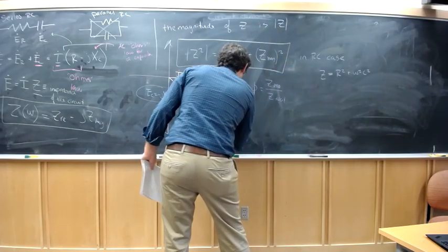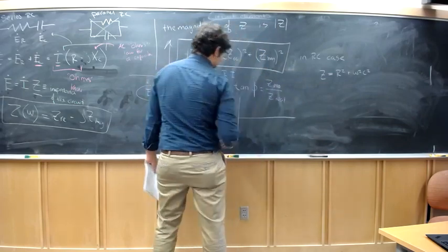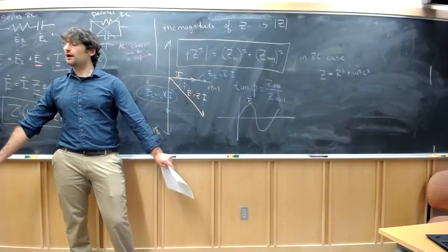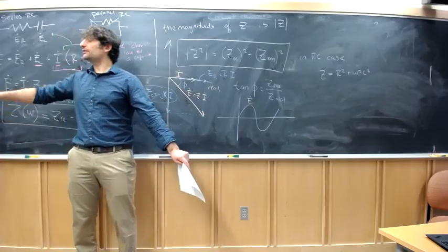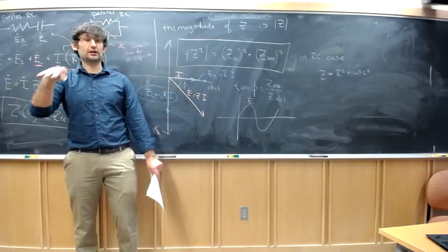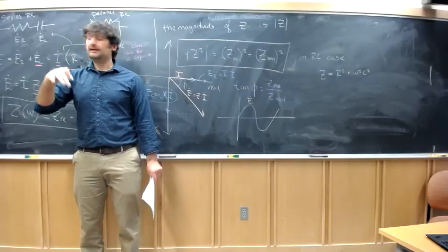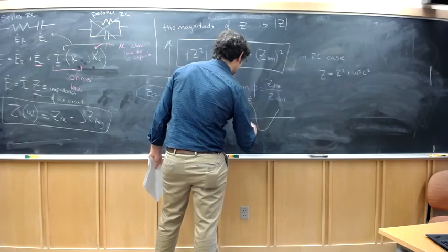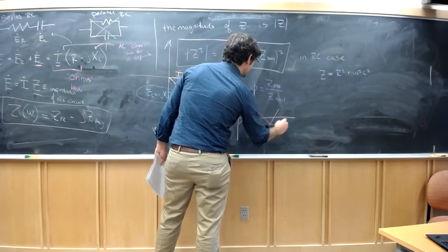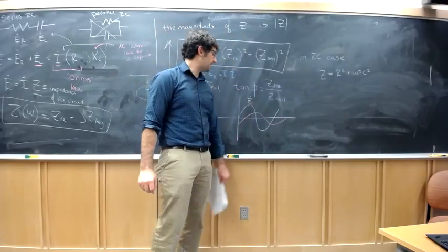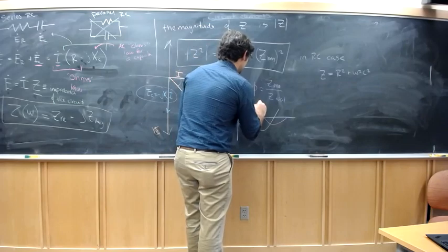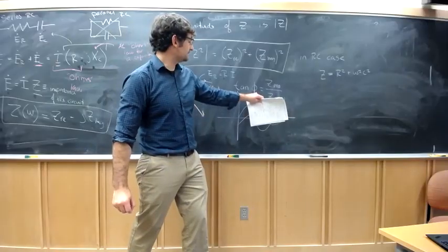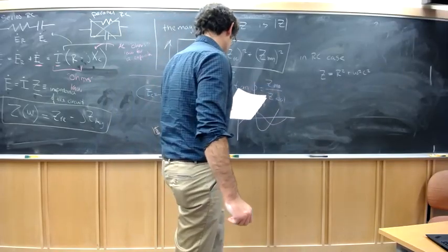So let's think about what the potentiostat's actually doing. We have our voltage perturbation that we're applying. We control that. We have a frequency generator that generates a sine wave in voltage that you're actually putting on your electrode and wiggling the potential, right? And then there's some current that comes off that, right, that might have a different phase and a different amplitude. And the frequency analyzer can just measure phi directly. So if you know phi, you can get the ratio between these things.